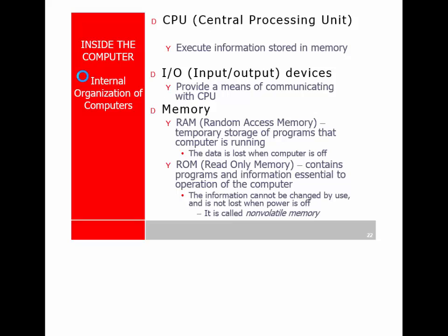So what used to be fixed in stone in the early days of ROM, you could buy in two flavors. One was programmable, what they call OTP. You programmed it once, and if you made a mistake, you threw the chip away and did it again. That was usually what OEM manufacturers would buy because they were cheaper than the next type, which was erasable. And the way we used to erase those is you put them underneath a tanning booth type light, although in Malaysia you don't need tanning booths.